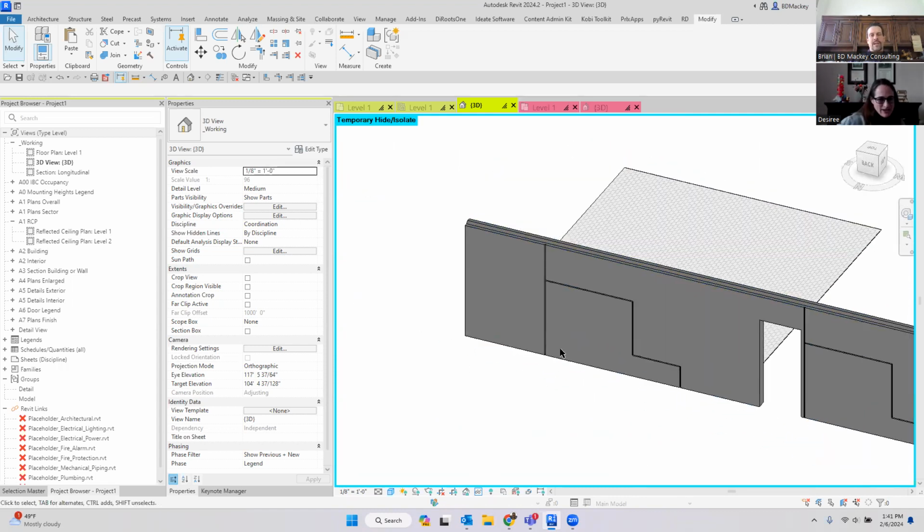So anyway, there you go. That's my solution, Rick. I don't know if that answers it. I don't know if Tom likes that original solution. But yeah, you can copy it. You still have to run the cut tool in mine all the time. Or if you've got a significant pattern of, like I said, vertical, vertical, horizontal, just go create a wall or a face-based family, place it on there and copy it around and be done with it.